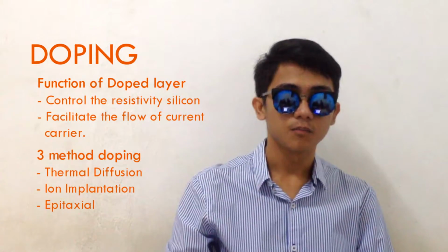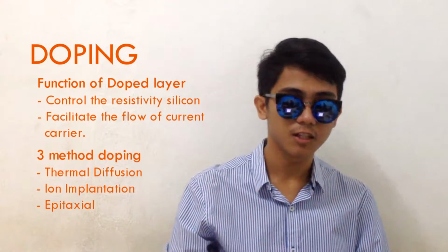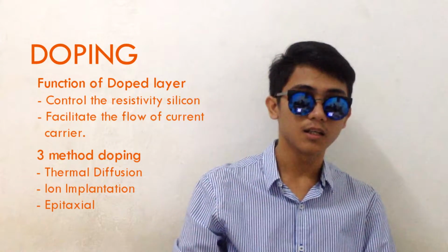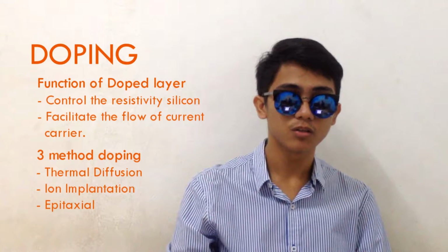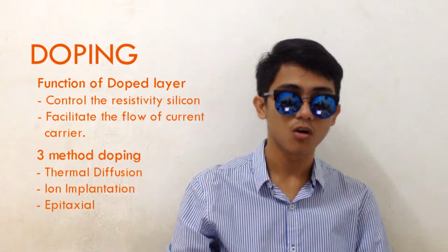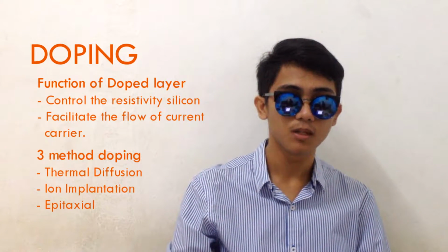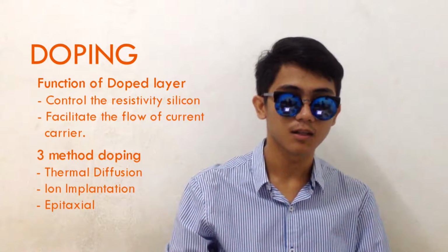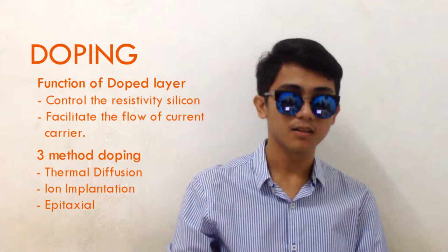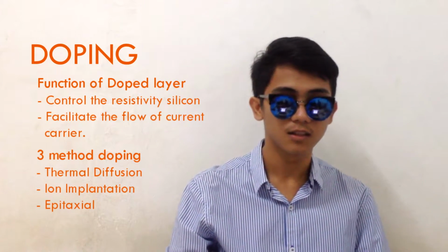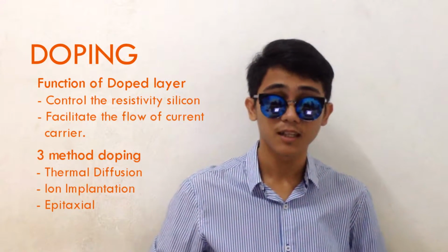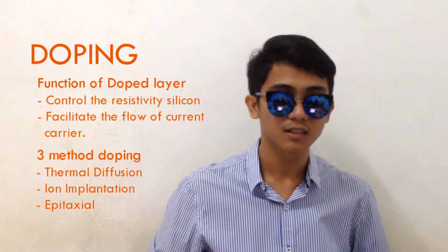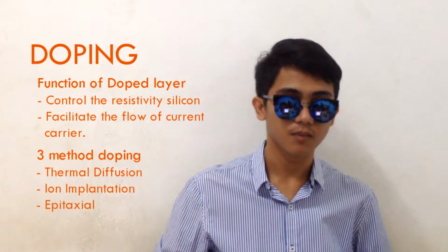Thermal diffusion, advantage and disadvantage. The advantage is the ability to introduce a very high concentration of dopants into the polysilicon layer, attaining a low value of resistivity. The disadvantage of thermal diffusion is the high processing temperature and the tendency to increase surface roughness.